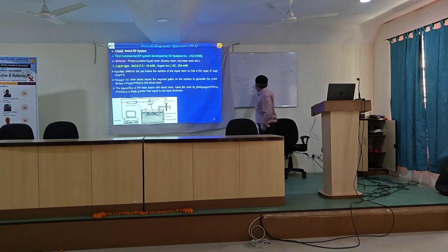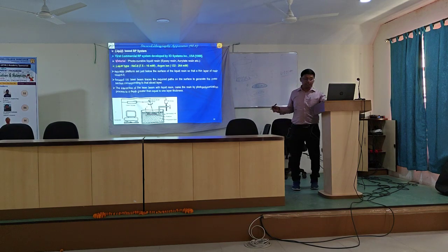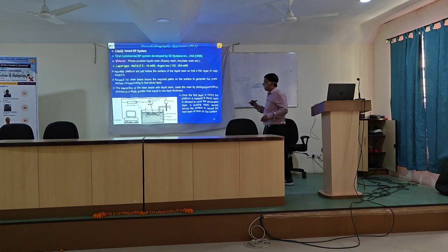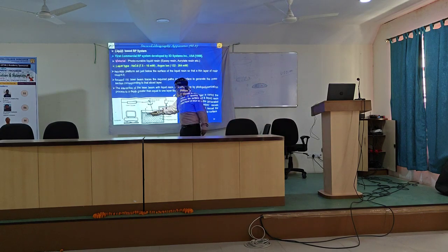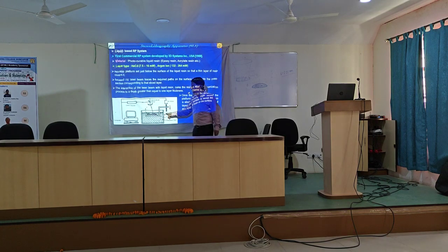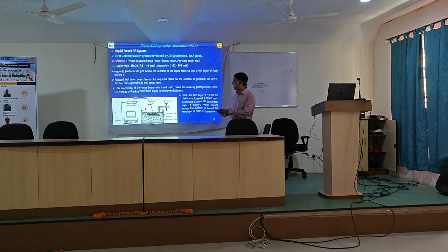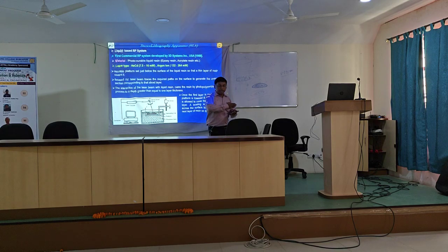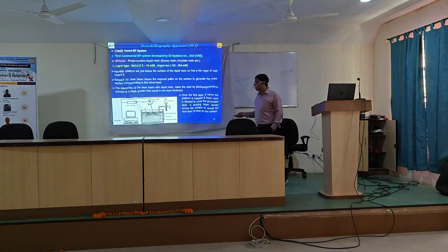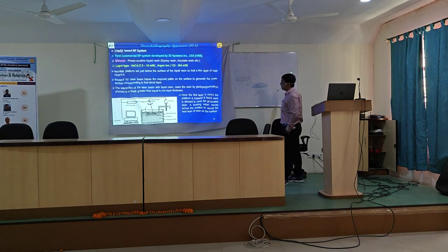Due to the interaction of the laser and the resin, the photopolymerization process starts and it will cure or partially cure initially. Once one layer is over, the platform will lower down by one layer thickness, that means 0.01 millimeter, by a CNC system and screw nut mechanism. The liquid resin surrounding the first layer will cover it, but that process is very slow. To make it fast, a leveling wiper, a leveling blade, will move from one end to the other so that it deposits the new layer of resin, with thickness equal to 0.01 millimeter.